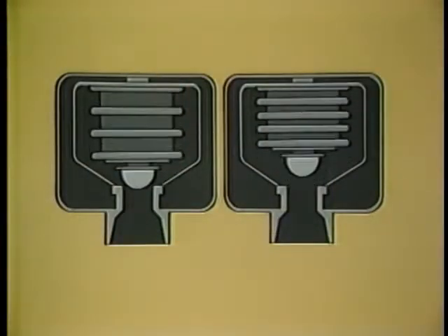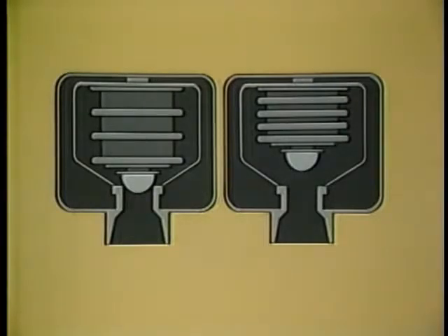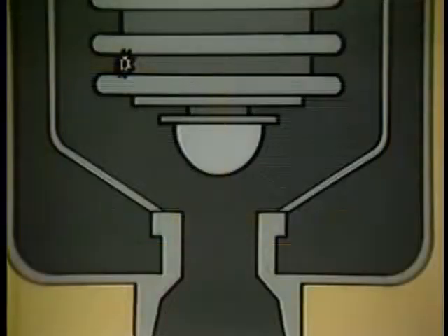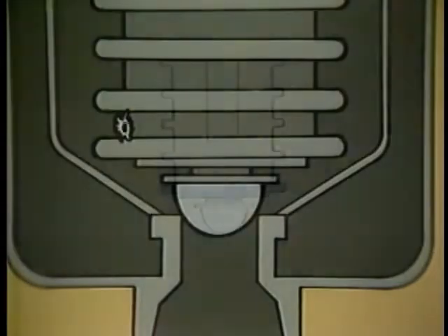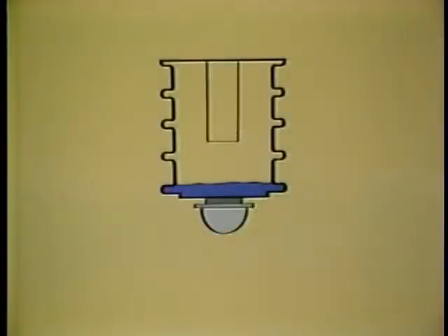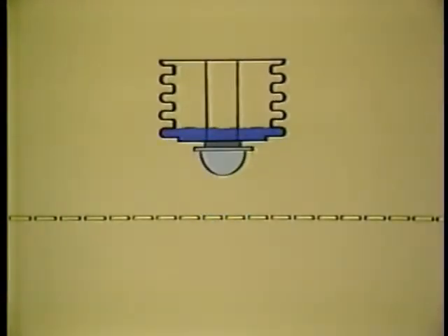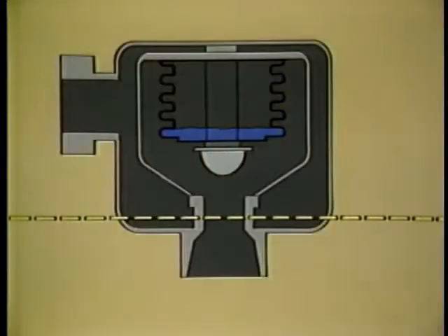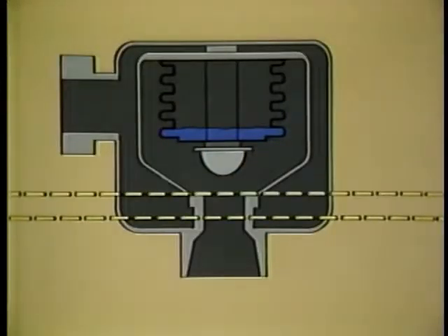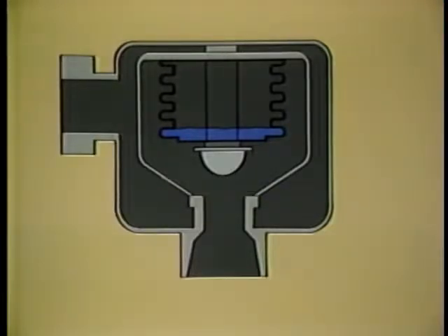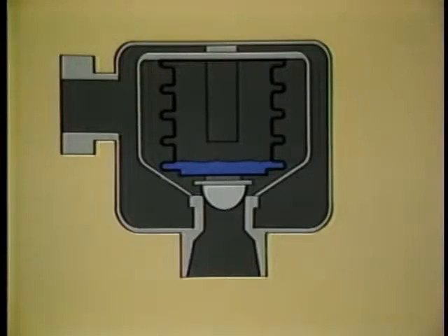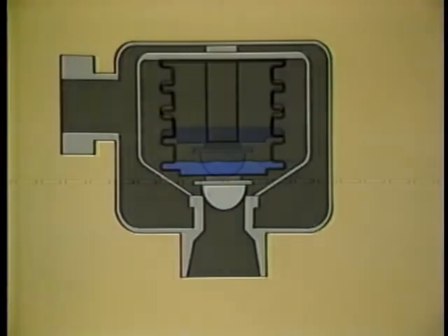There are two methods of constructing a bellows trap which determine, among other things, how the trap will fail, open or closed. In both methods, the liquid charge is added and then a vacuum is drawn in the bellows, compressing it to an internal stop. Only water is used as the bellows charge of the trap which will fail closed, and the valve is positioned to seat just short of the bellows free length. If the bellows ruptures, it returns toward its free length and the trap is closed.